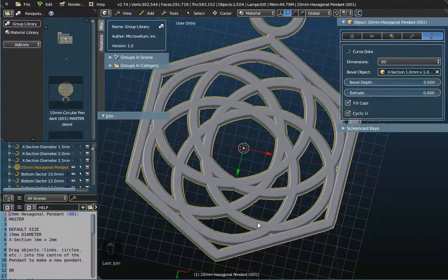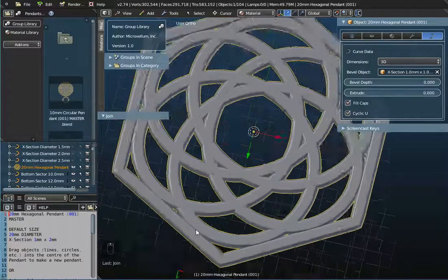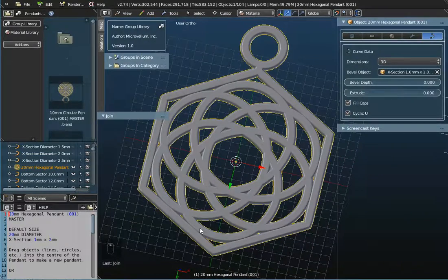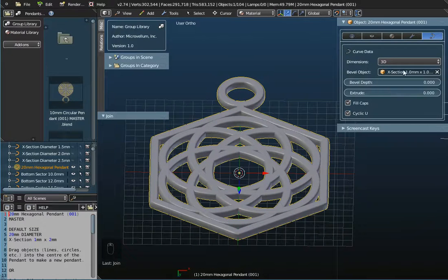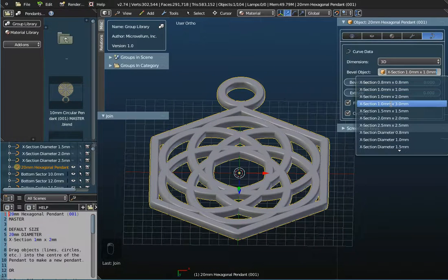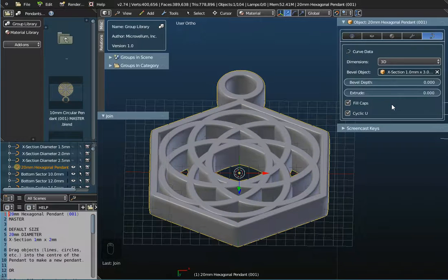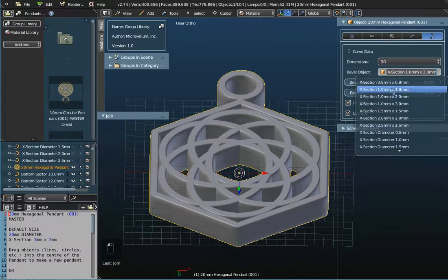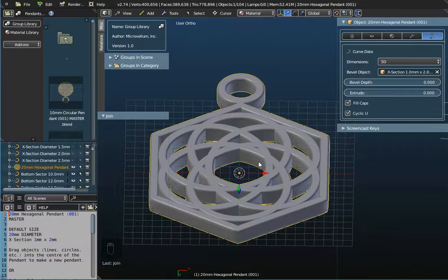If you do that, make sure that it is still overlapping here, because that's very important from the point of view of the object being 3D printable. So, or you could change it to 3 millimeters thick, for example. But I'm going to leave it as 2.